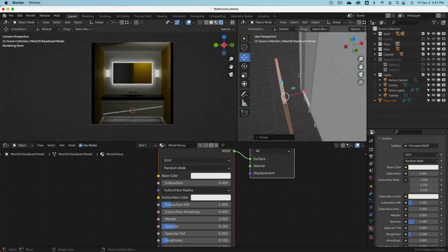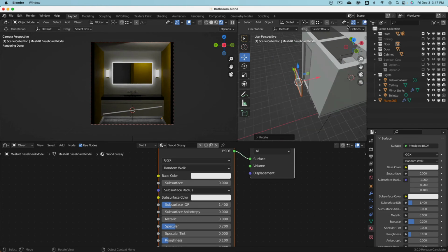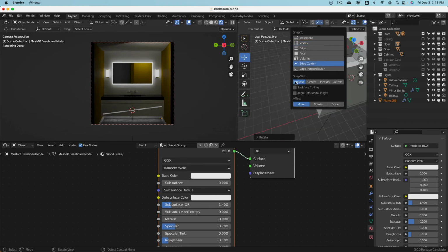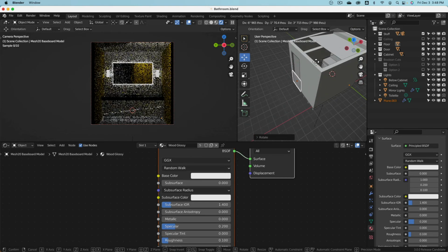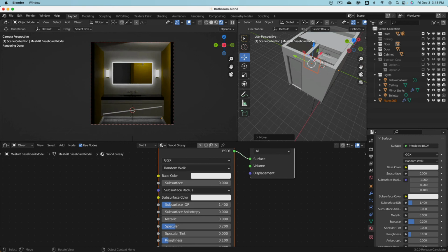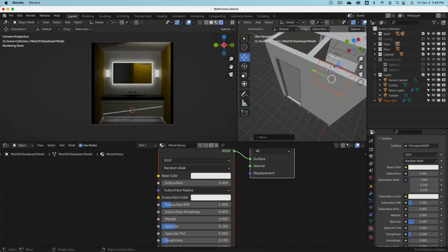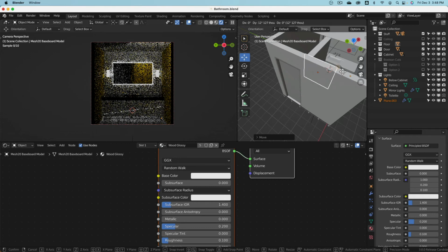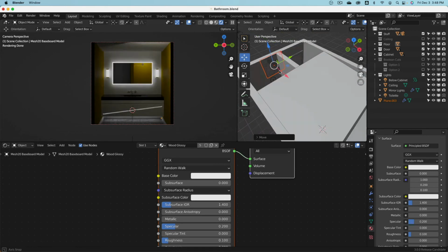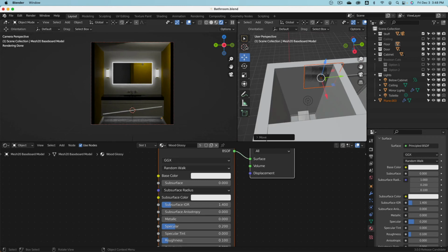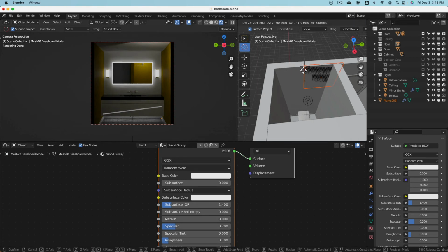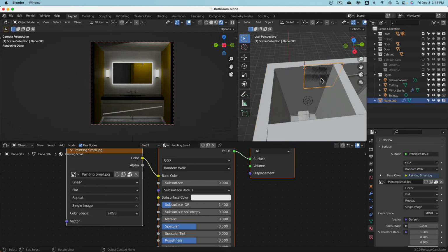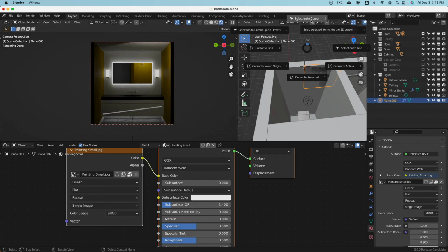Now to position this again nicely, very easy. And this is one part in SketchUp that works better, hands down. So snap to the edge, G, hold control. Now go to here, G on control. Oh, it snaps that point to there. Oh, that's irritating. Okay, what's a different way how we can do this? 3D cursor, hold control, move, hold control. There it snaps actually to that edge. Very good. Then select the painting, Shift S, selection to the cursor.